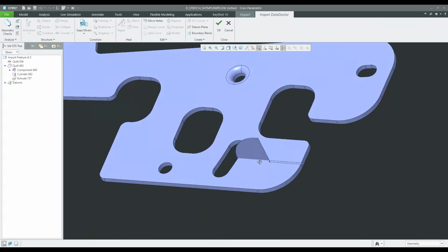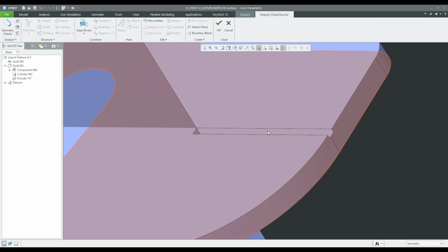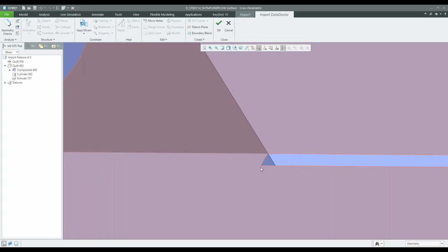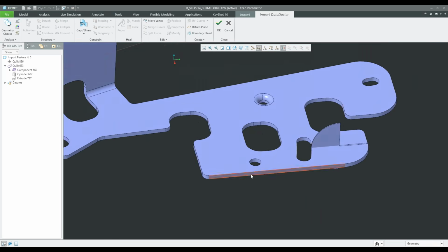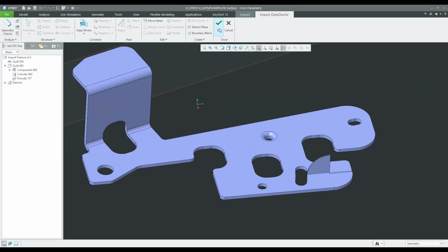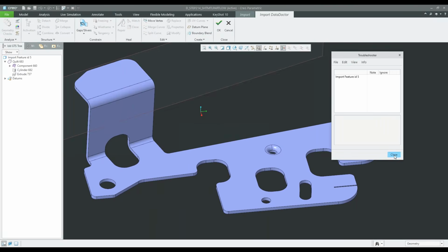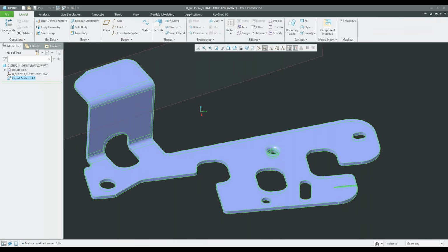There we go. So we basically grab this bottom flat surface and the surface loop around it, and then selected an edge on that cut feature that we wanted to use as an axis to create our revolve. So, yep, that's basically it for that. So I could get rid of that guy, and I'll go back into here and say, geometry checks, everything looks okay here, complete this, then click that green check mark.